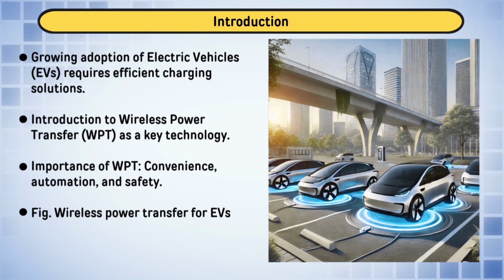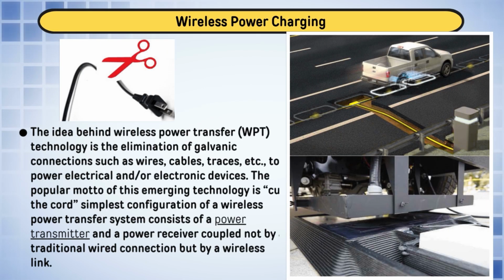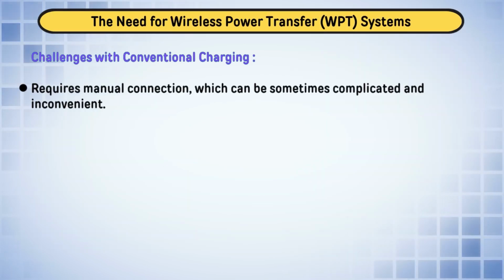So, from the PV cell we have to charge the battery, and when the vehicle is operating in braking mode we have to charge the battery. However, when this vehicle is operating in motoring mode we have to draw power from the battery. So, this bidirectional DC-DC converter should operate both ways. Therefore, the application of these DC-DC converters in electric vehicles is very important.